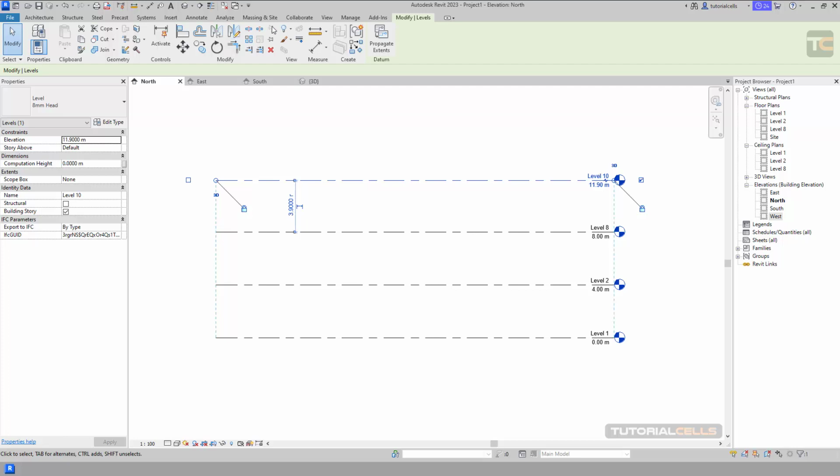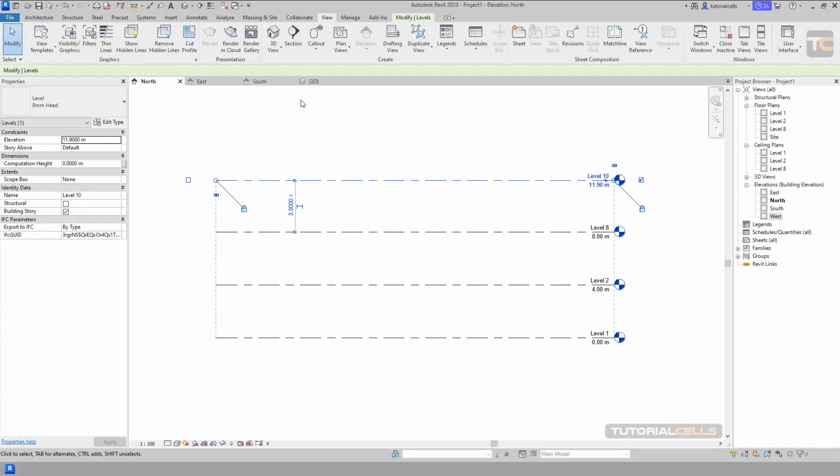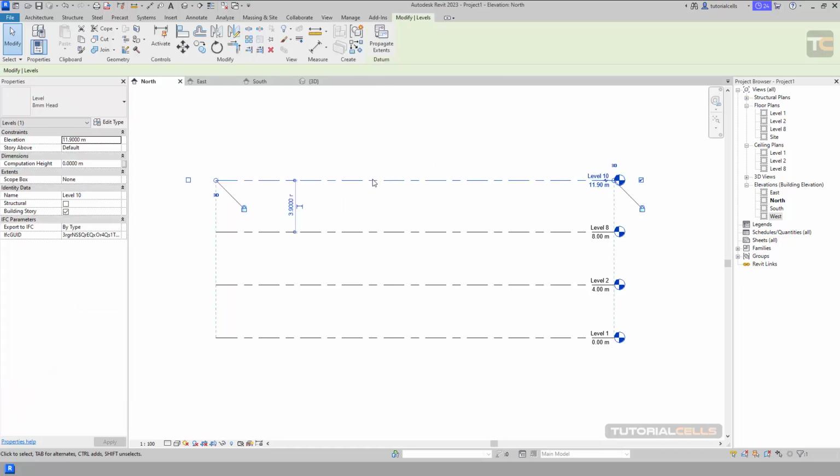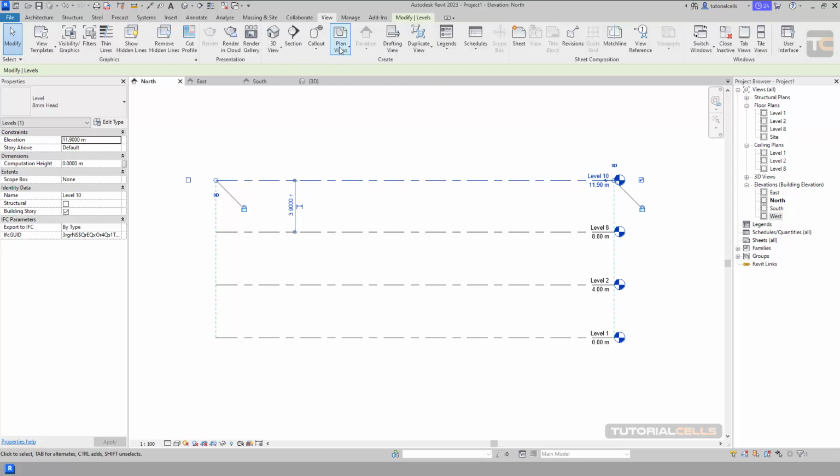view, and let's here, plan views is here. Okay, you want to create from this line because, as you can see, it's black. Select it. We want to make from this level floor plans and ceiling plans. Okay, so go into view.